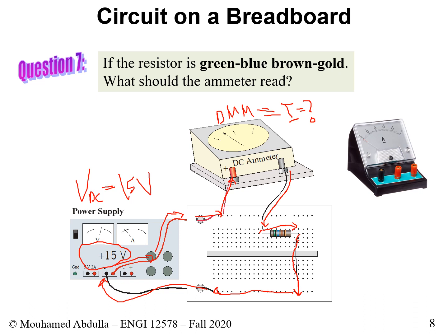So through Ohm's law, we know that we need to have two of the three variables. So we have Ohm's law, which tells us V, maybe I could write it here, V is equal to Ri, or if you want I, because we want to find the current, is equal to the voltage divided by the resistance. Voltage we know, voltage is 15, resistance we don't know, but we're told the color code, right? It's green, blue, brown, and gold. So let me just bring the pointer here. Green, blue, brown, and gold.